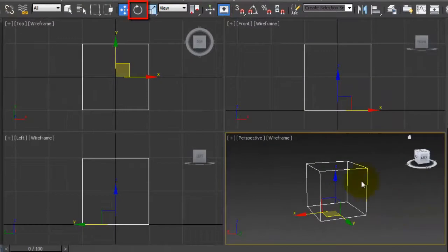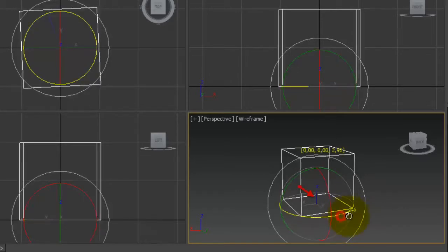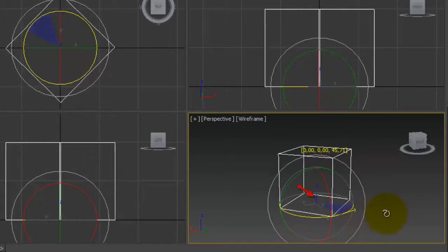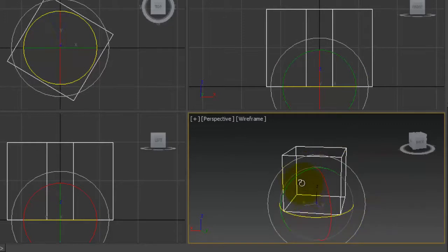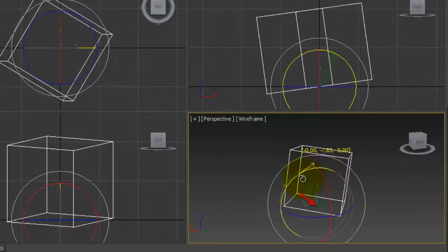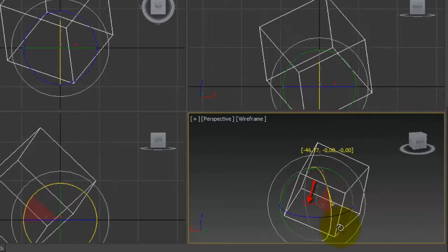It's a much simpler matter for rotation. From the toolbar, we access the tool by clicking on the icon shown. In this case, the gizmo has a different appearance, but there's no need for alarm. It's actually very simple. If we bring the mouse towards one of the colored axes, in fact, the system identifies which axis the rotation occurs around. By dragging, the object can be rotated both in one direction and the other. Just like before, the color blue identifies the rotation axis Z, the color green the rotation axis Y, and the color red the X axis.